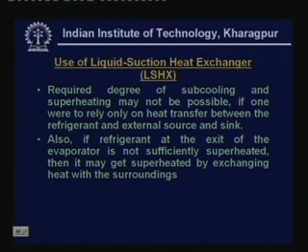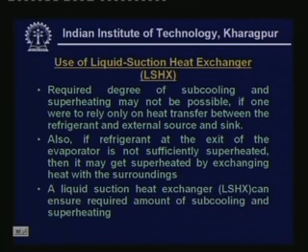So that is what is mentioned here. Required degree of subcooling and superheating may not be possible if one were to rely on heat transfer between the refrigerant and external source and sink. And also, if refrigerant at the exit of the evaporator is not sufficiently superheated, this is another reason why we need a liquid suction heat exchanger. If the exit is not sufficiently superheated, then it may get superheated by exchanging heat with the surroundings, which, as you know, is useless superheating. So a liquid suction heat exchanger can ensure required amount of subcooling and superheating. Let us see what is a liquid suction heat exchanger.